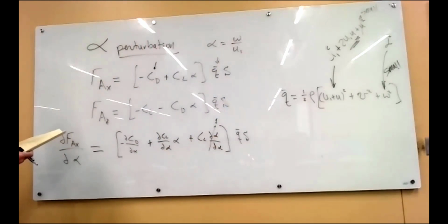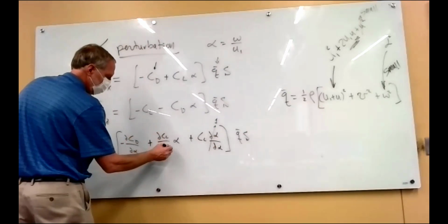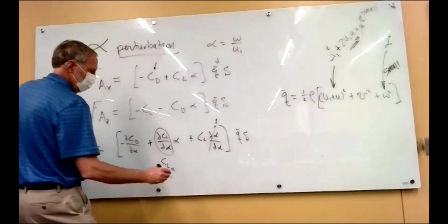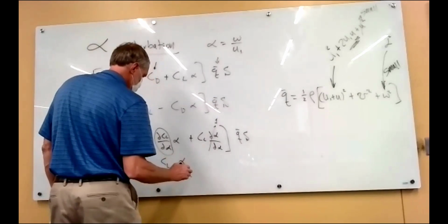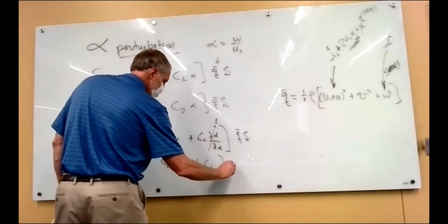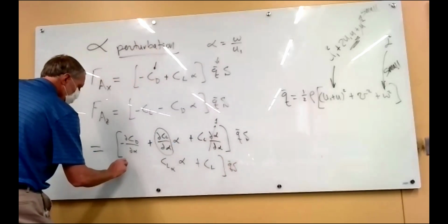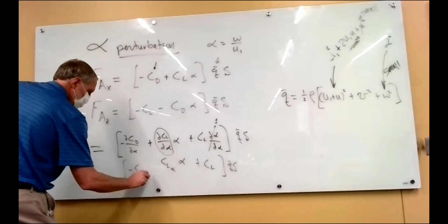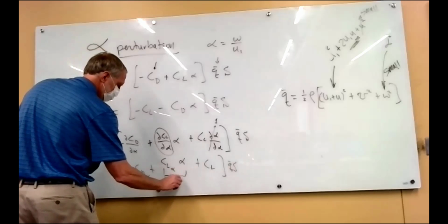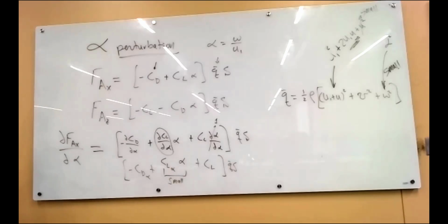And now this takes a little bit of explanation because we know that this change is important. That's CL alpha times alpha. And here's CL. And then this is CD alpha. But the book's going to say, well, we can say this is small. But that's the little change in lift. Now that's not the full alpha, remember. This is a small perturbation alpha. So that's not the total lift, that's the little change in lift due to alpha.